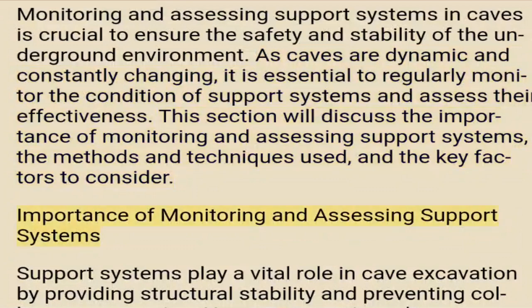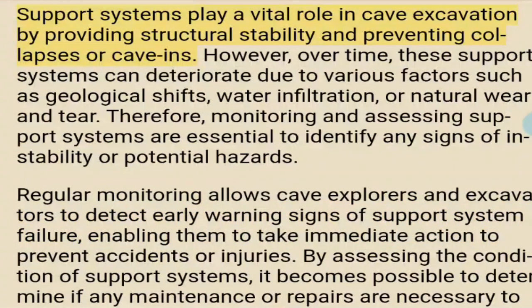Importance of monitoring and assessing support systems. Support systems play a vital role in cave excavation by providing structural stability and preventing collapses or cave-ins. However, over time, these support systems can deteriorate due to various factors such as geological shifts, water infiltration, or natural wear and tear. Therefore, monitoring and assessing support systems are essential to identify any signs of instability or potential hazards.